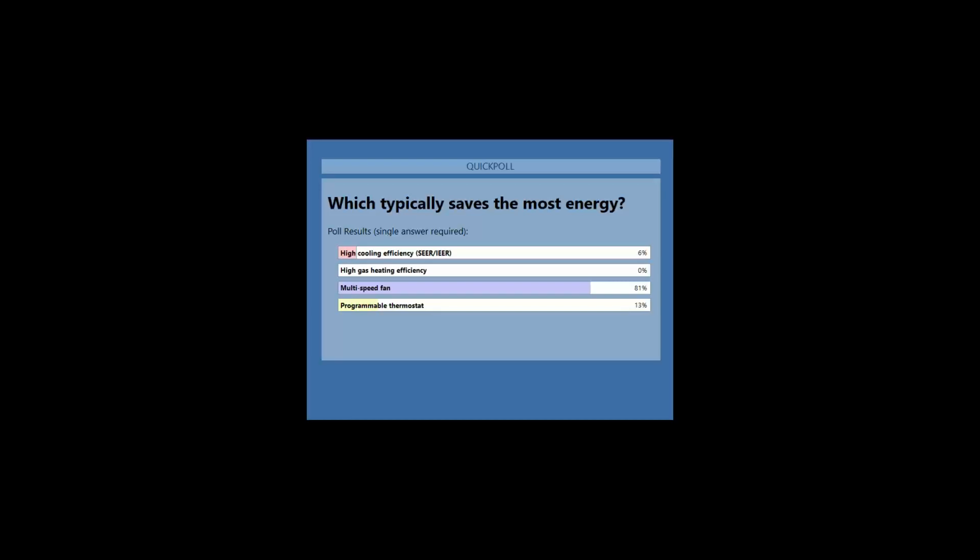If you have old compressors like this, reciprocating compressors, the only thing I want you to know is that you can add unloaders to them easily as a retrofit to give them more stages. Just know there's 2 kinds of unloaders, pressure unloaders and electric unloaders. Pressure unloaders are for constant volume equipment. Electric unloaders are for variable air volume equipment, and you can never use the opposite the other way. If you have any questions on that, ask me. These are becoming more and more rare, so I'm not going to spend more time on it today.